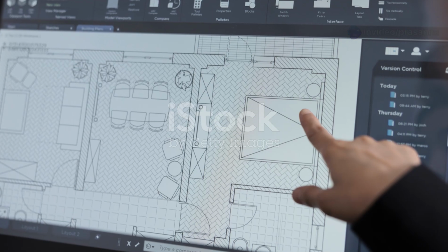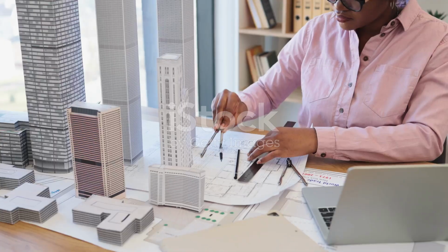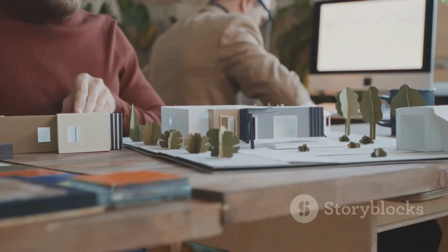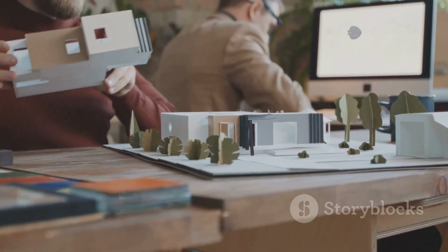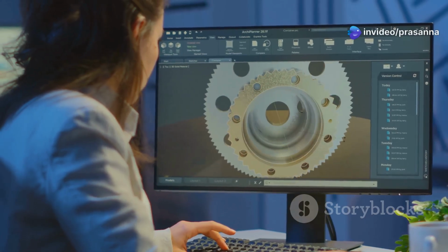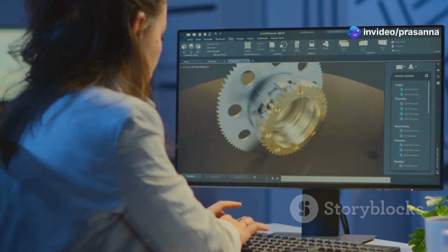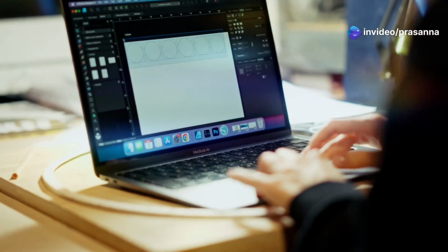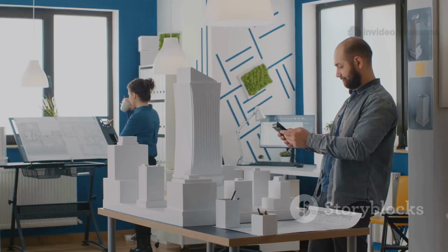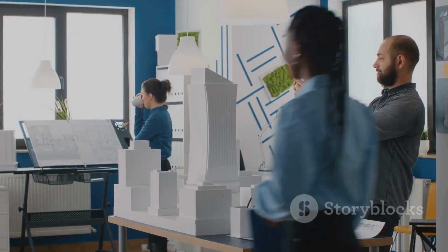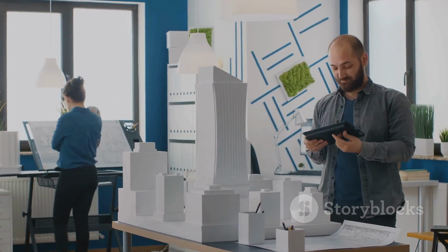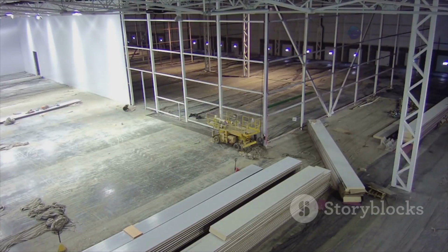With your 2-dimensional floor plan traced in SketchUp, it is time to build upwards. This is where the magic of 3-dimensional modeling begins. The main tool you will use for this is the Push-Pull tool. This tool is a hallmark of SketchUp's simplicity. Select a flat surface like the area representing a wall section. Then use the Push-Pull tool to pull it upwards.